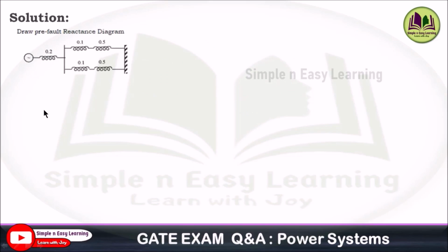Solution. Draw the pre-fault reactance diagram from the single line diagram given. The generator reactance is 0.2, transformer 1 reactance is 0.1, line 1 reactance 0.5, transformer 2 reactance 0.1 and line 2 reactance is 0.5. Now we can simplify this reactance diagram. These two are in series, so it becomes 0.6, and also these two are in series, it becomes 0.6.